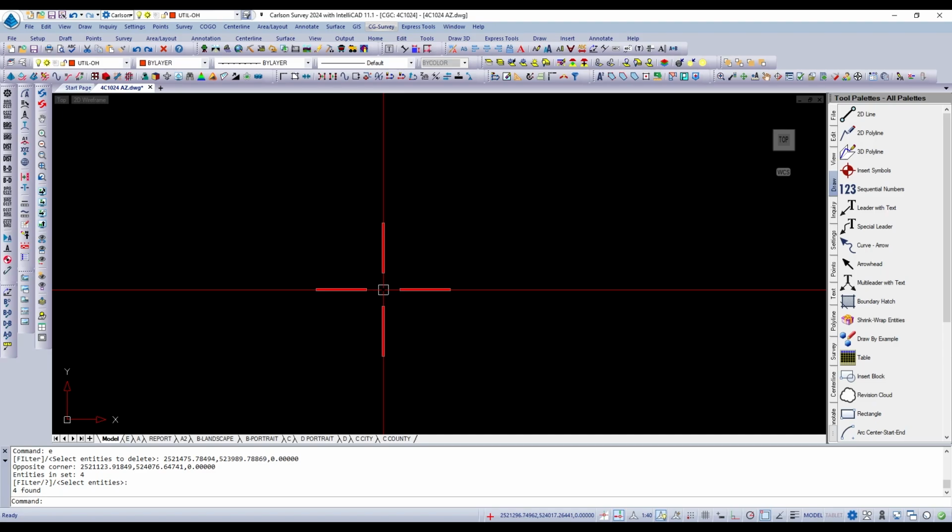You can get all kinds of different programs that will accomplish different things to run within or on top of the CAD program. Same thing with AutoCAD. So I'm using a civil engineering suite, but you can get architectural software that runs on top of it that's going to typically be running in feet and inches instead of feet and decimal feet like we use.